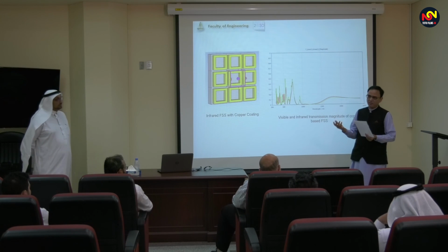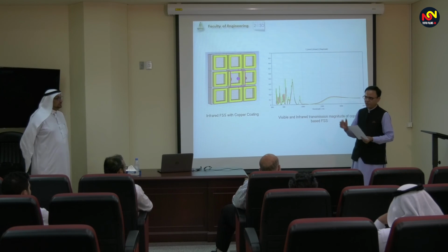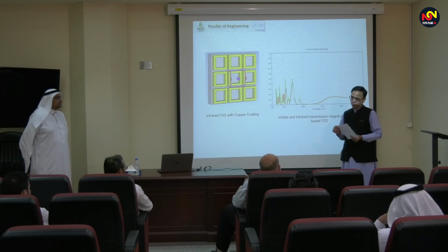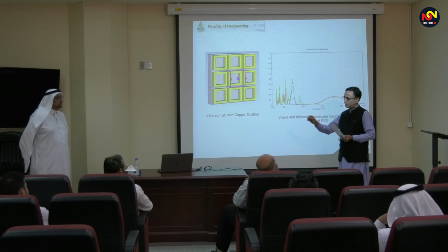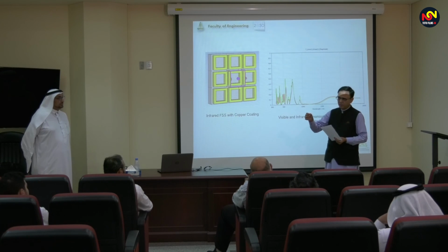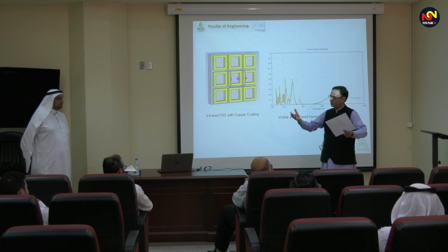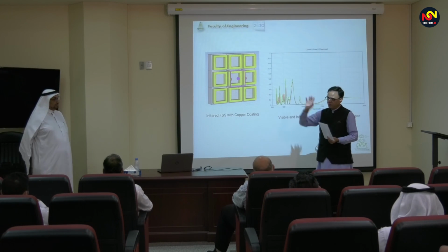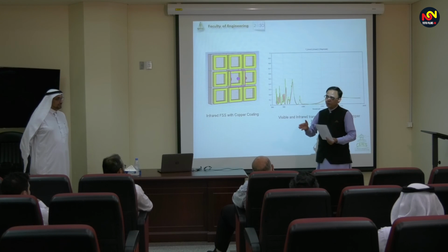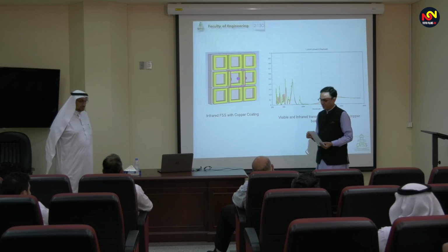The cost and the power, even in microwave regions, if you have an active FSS, are big problems. You have to be very careful about the power, the DC voltage, how to give it, and the power dissipation in the diode. If 1 diode costs $1, and we have 20,000 diodes in the size of that TV screen, you have to spend $20,000 only on the diodes.